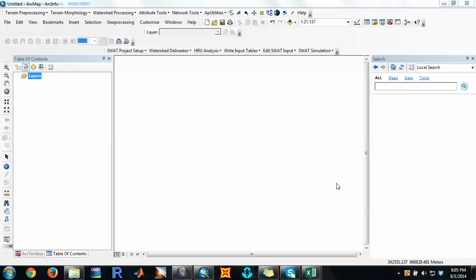Hello, in this session we are going to see how to input the data into HEC-RAS and how to run the model. Particularly, we can export or import data into HEC-RAS in one of two ways. The first one is if you are given a topo map or digital elevation models, you can create a TIN map, or triangular irregular network map, and you can export that into HEC-RAS in a GIS format, and then you can work on that.